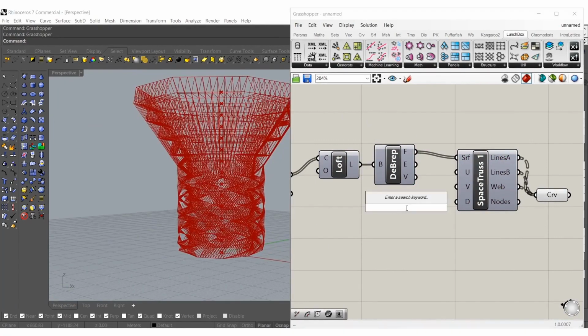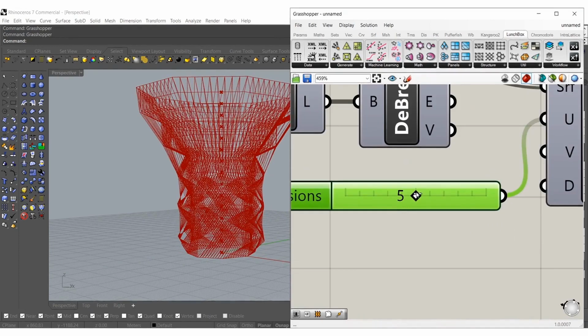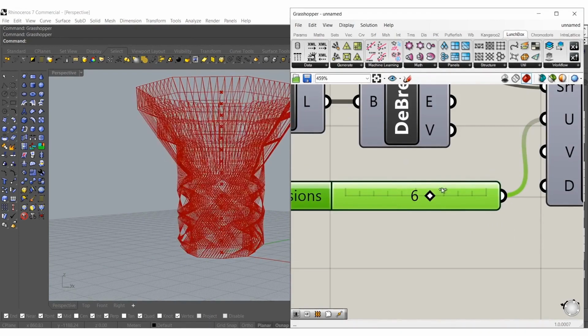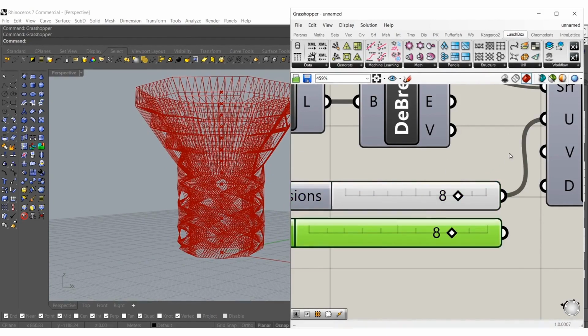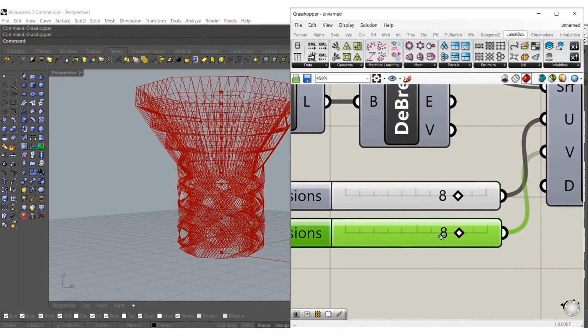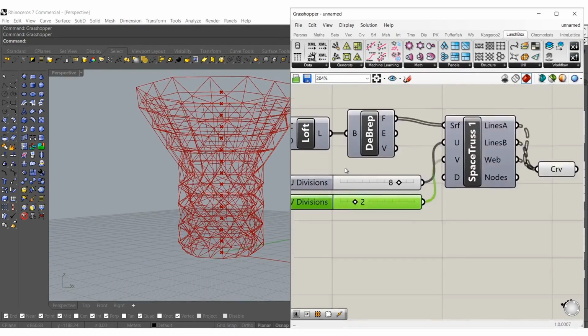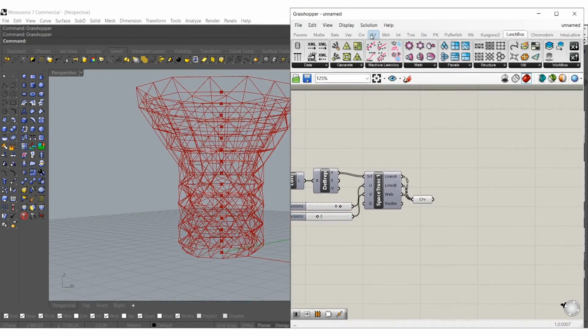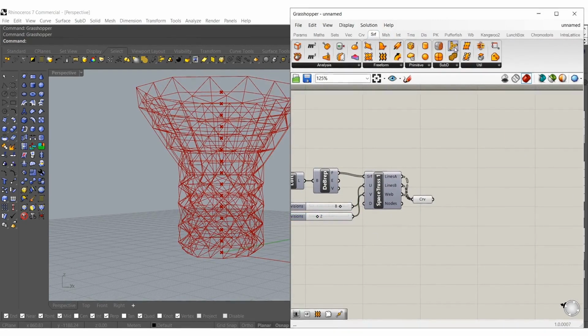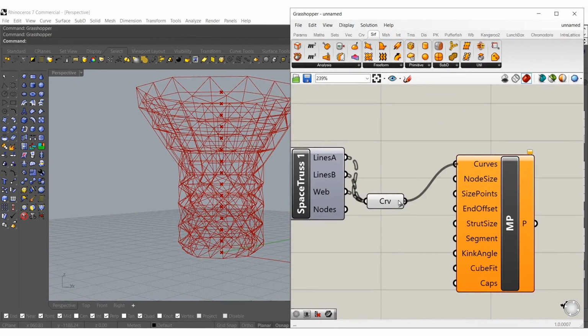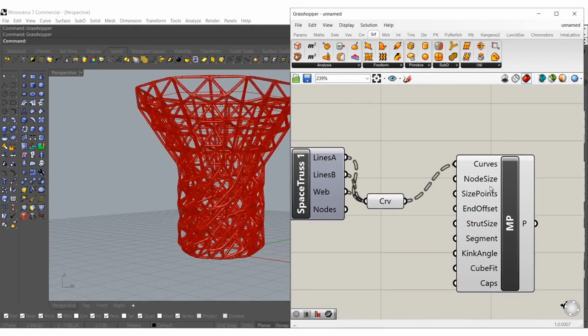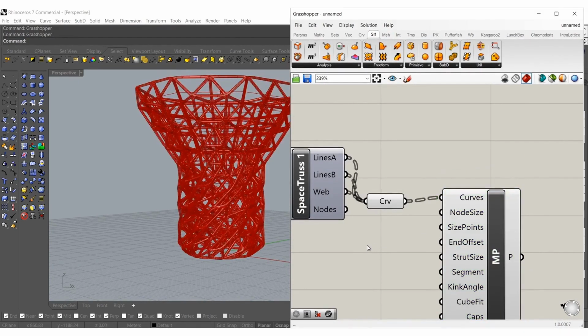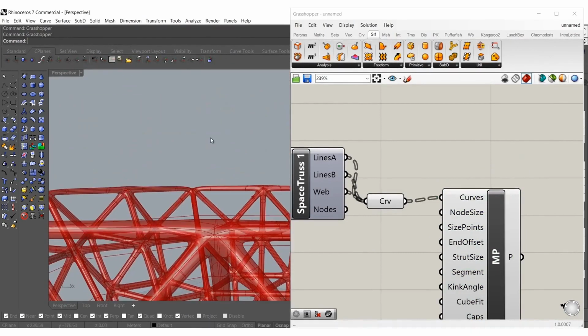Okay, and let's mess with our UVs. Keep those relatively high. I imagine the V will leave it down at like 2. So we can start to see geometry. And then if we go over to our surface tab, multi-pipe for Rhino 7, this would be our SubDs. Give it a moment. That's looking connected. I don't think we have to flatten it out.